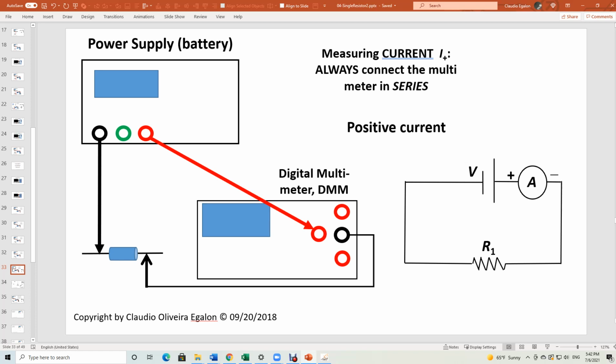Okay, and let's just measure this resistor. I'm suspecting that it's not 10 ohms what I have here. What I have here is what? Ohms. I can measure my resistance. Oops. Okay, this guy here is 266 ohms. So close to 270. Close to 270.